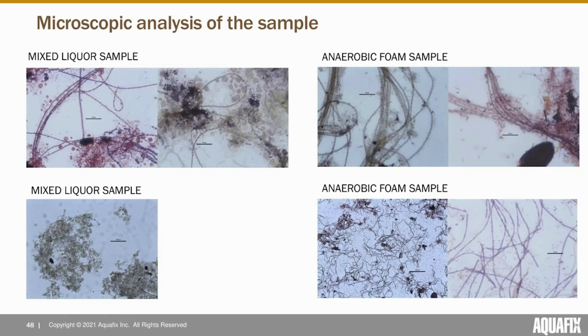It's interesting because you have to keep looking at a bunch of different things, and you should never make an assumption as to what's going wrong in the digester. Initially, if I hear about foaming in the winter, I think, oh, there's a temperature drop, and then I'll look for filaments. Hey, there's filaments present. By the way, Microthrix actually likes cold temperature too, so that would be another potential winter foaming issue you could see. But you can see we have very high levels of filaments here, and they were only a partial contributor. Filaments are very rarely the only thing in question, but they tend to contribute greatly. So it was just an interesting case.